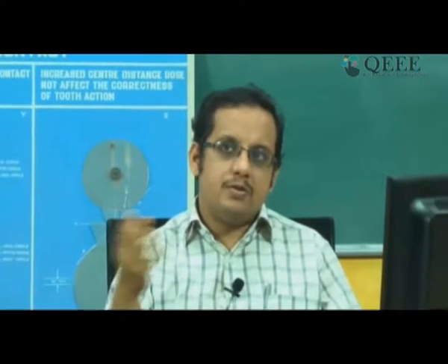You wish to control the torque and the speed ratios, right. So, in case you want more torque when your vehicle is moving uphill, you would go to a lower gear, and in case you want a higher speed, you go to a higher gear. As a result, if both gears have the same radius, then omega 1 will be equal to omega 2, and torque from gear 1 will be equal to torque from gear 2. You will not get a gain either in torque or in velocity. So you might as well do away with a gearing arrangement where the gears have equal diameters.